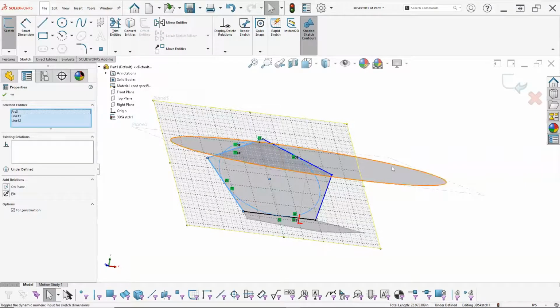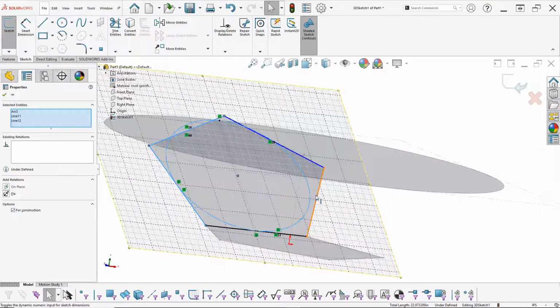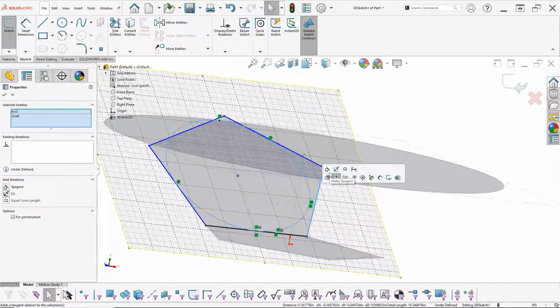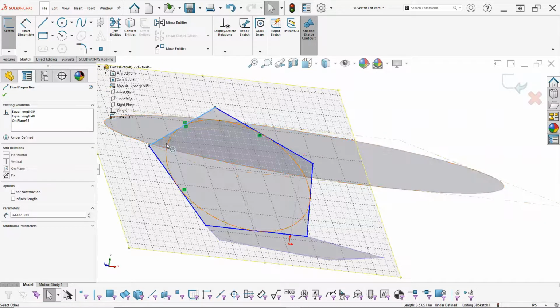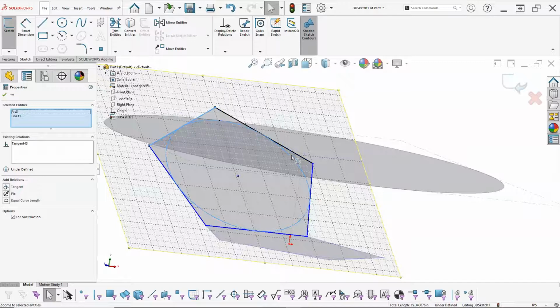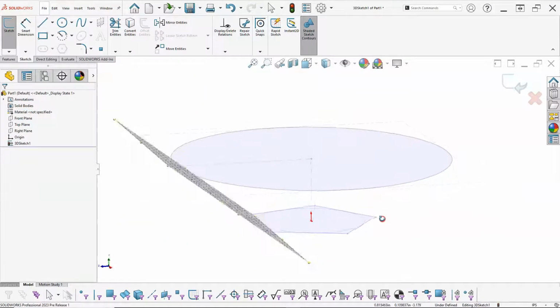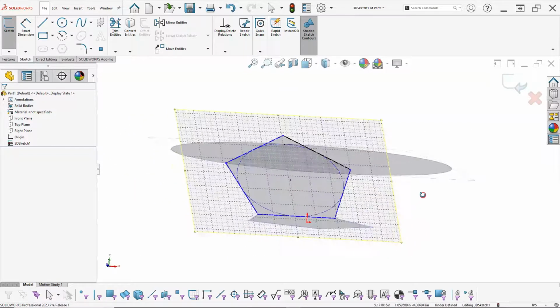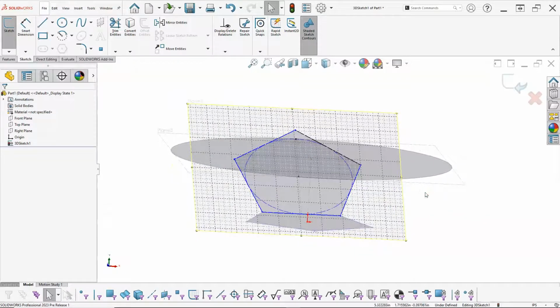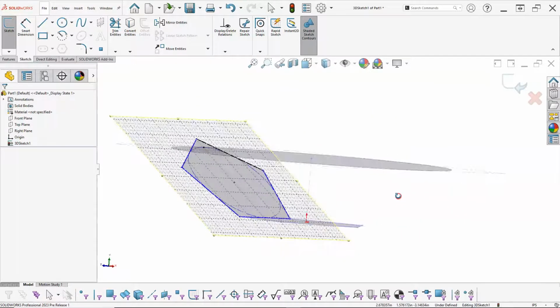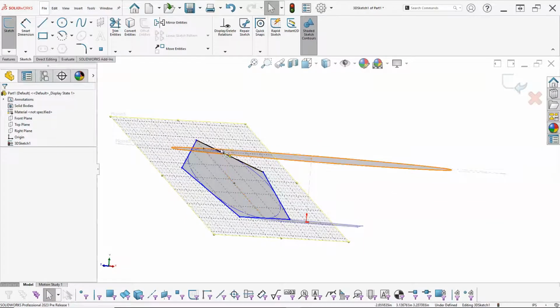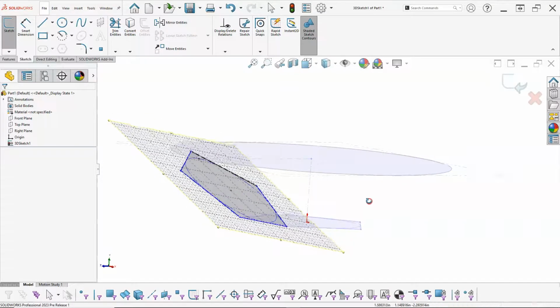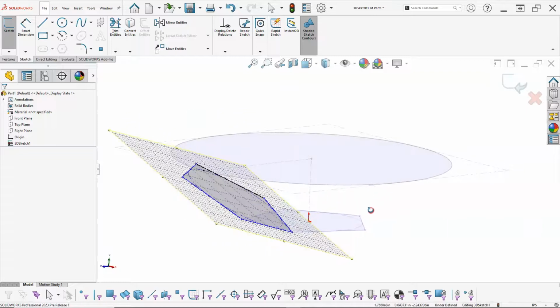And it gets a little bit confusing. Okay, it gets a lot confusing. Alright, so let's go back over here, tangent, and make sure that I'm getting all of these selected. I don't see any tangent popping up, so I didn't get that applied. And let's see, do I want the circle or do I want that point? Well, part of the problem is when we create the surfaces, these aren't going to be exactly through that plane, so we'll need some construction geometry to define it.